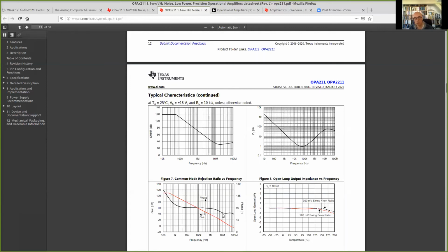And so usually, as a rough rule of thumb, you want to model 10 times more than the bandwidth you need. So if I want to make an application for 10 megahertz, then I would like to have a model up to 100 megahertz.